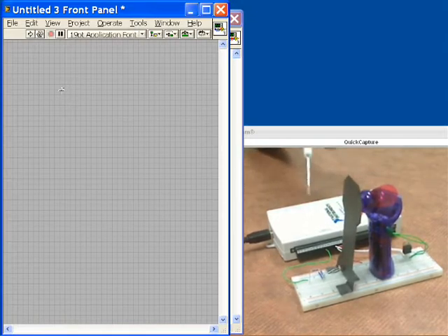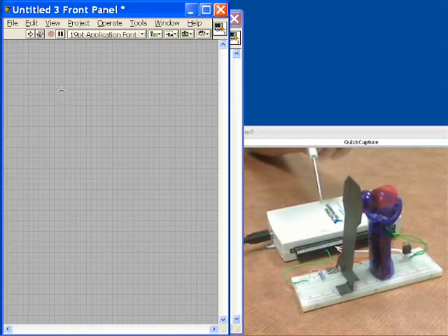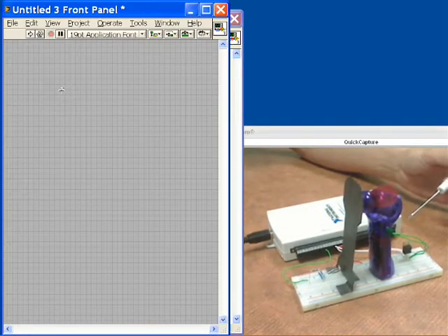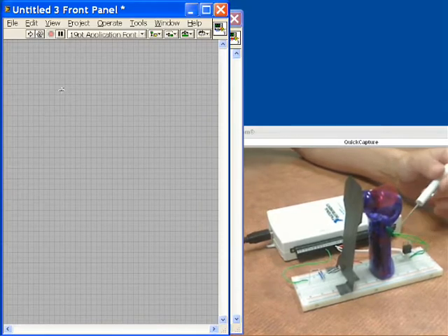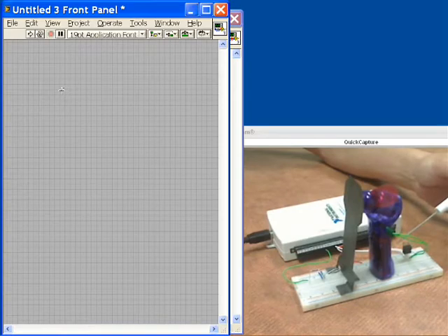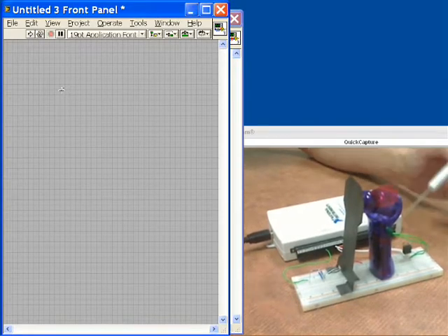So the way the setup is with the USB-6211, we're taking an analog output channel, and over here we're coming into a power transistor. It would be nice if we could just drive this directly with the analog output, but these bus power devices of course don't have that kind of power. So instead we're going to use the batteries that are inside the fan to power the motor, and we're going to modulate that with a power transistor.